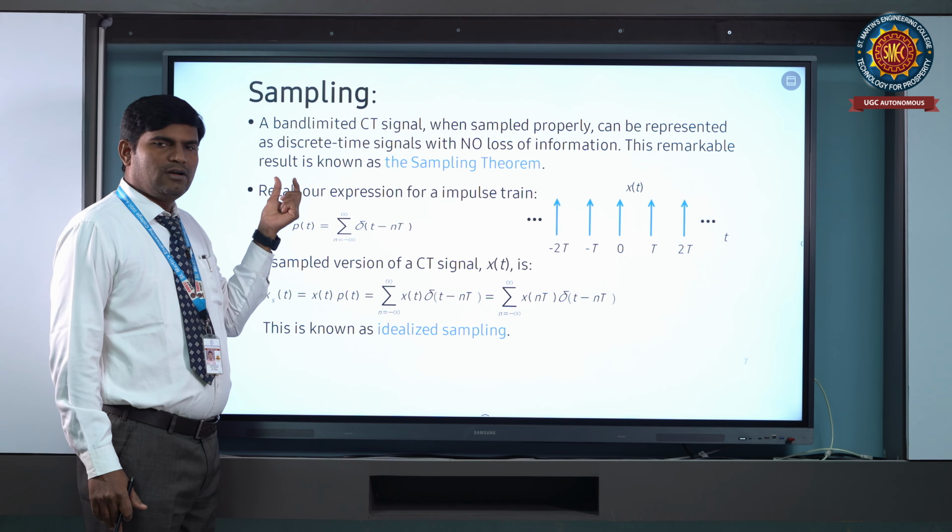Since our signal is band limited, and noting that the condition omega s greater than or equal to 2B is maintained, that is, 2 times the maximum frequency, where the maximum frequency is B here, we can use a low pass filter with cutoff frequency B as a reconstruction filter.